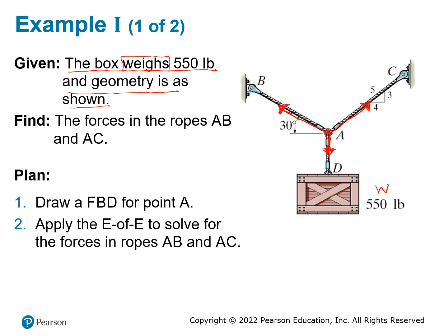So you do the free body diagram, you simply draw this is the point, a particle that we are interested in. We have three different forces connected to this point. This is our FAC, this is our FAB, and this is our F of AD, which is equal to 550 pounds. All these should be vectors. So if I draw this one as a vector, and I put this one as a vector, then I have to put this one as negative 550 j.